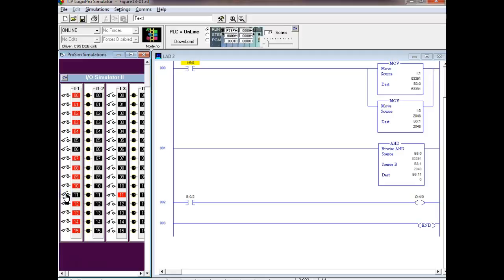So if I get back a 0, what does it mean? I could come up here and, what's it doing with all these other, this guy's closed. Well, I'm not checking that bit. I'm not checking this input. I'm not checking this input. I'm not checking that input. I'm not checking 4. I'm not checking 5. I'm not checking 6. I'm not checking 7. I'm not checking 8, 9, 10. I'm checking to see if this guy over here is either open or closed. Right now, my 0 flag's not working, but it should have worked. If this bit comes up to be set, that means that sucker is closed, right? You understand? If it comes up and gives me 0, it means that it is open.